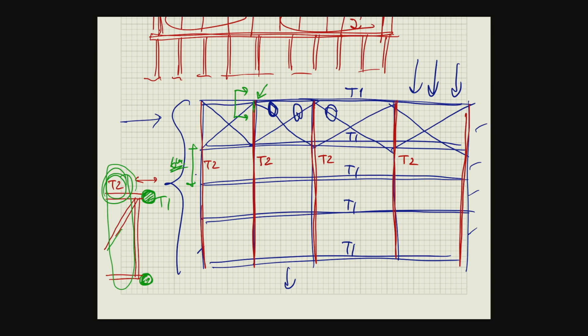Now, you have 4 repeating bays, and 1 bay is braced. Okay, you can find the size of these bracing members using what? Generally, the bracing member is the tension member. So if one is bracing, another will not be working, right? It depends on the direction of the force. So if you have the panel like this, and if you apply force like this, one under compression, this one tension, the tension one is going to carry the load.